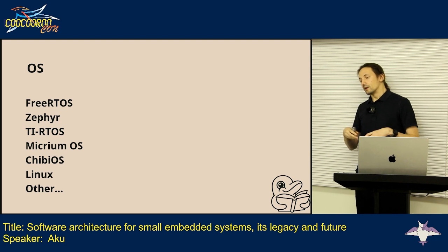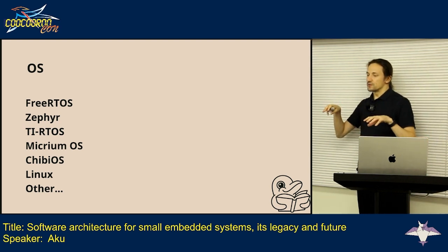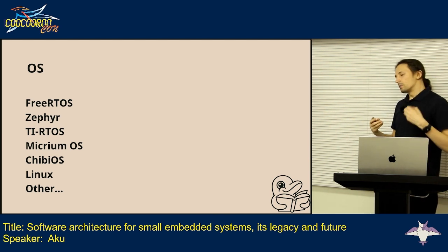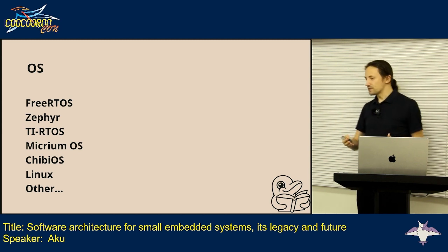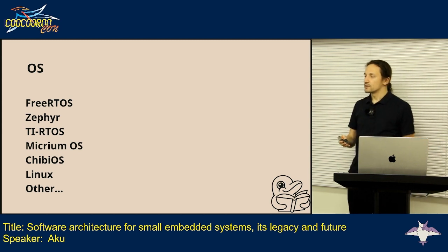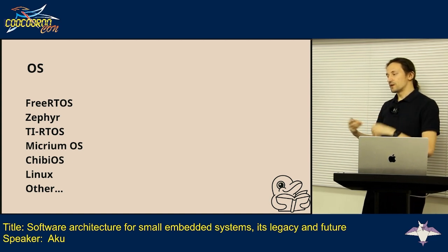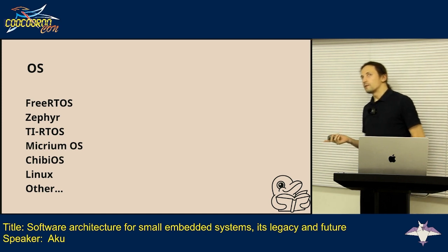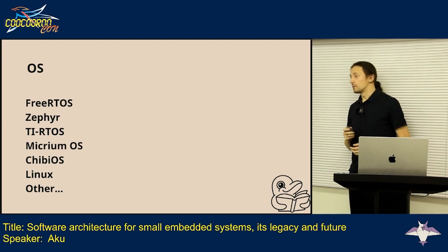Instead of having, let's say, 10 microcontrollers doing different jobs, but just one task each, we started to think about, okay, now we have this new set of tasks. We would like to have microcontrollers that actually can process more and can perform multiple tasks simultaneously. And that's where ARM M cores arrived, and they brought us native support for different real-time operating systems.